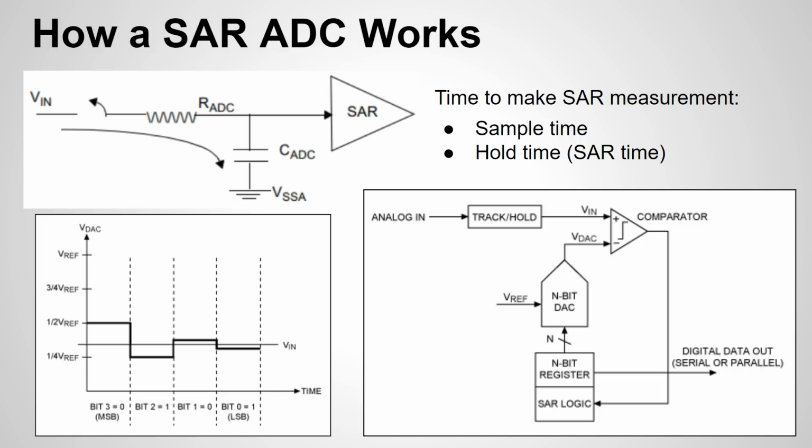And then the hold time, or the SAR, where it does the calculation of the value, is then done. So we're charging our capacitor up to the voltage of the input. We then remove the input and then calculate the value based off that capacitor.